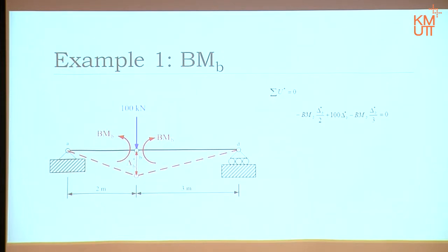Okay? The bending moment times the rotation theta here. However, this theta is equal to delta B over 2. Correct? That's the term delta B over 2. Because that one rotates anti-clockwise, but AB rotates clockwise. They are in opposite directions. Therefore, that work is a negative work done.